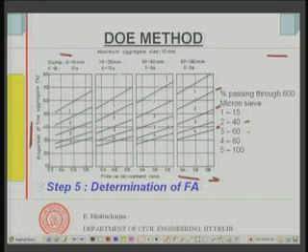600 micron, right. So, as you have finer sands, coarser sand, you require more quantity of sand in the coarse aggregate system. In the finer sand, you require less quantity of fine aggregate in the total aggregate. So, that means if you have something like a slump of, let us say, 70 or 75, somewhere in between this, or 100 millimeter, and you have got this fine sand,